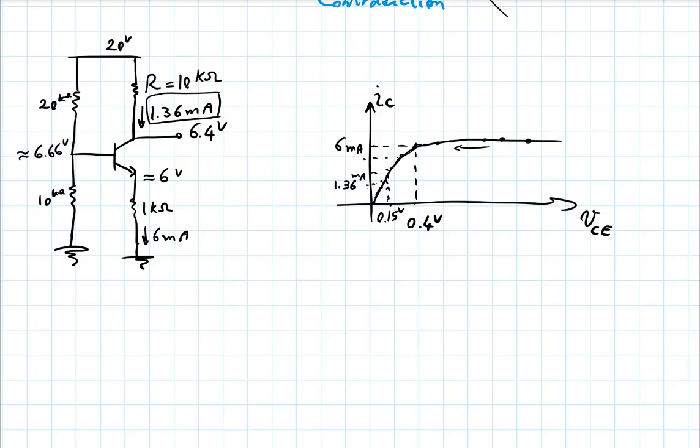This transistor is driven into saturation, and it has that kind of current at the collector. So again, to a very first order type of approximation. Recall again that a single curve like this corresponds to a single value of VBE. So in practice, maybe VBE is also changing in this process, which could make my point go from a curve like this maybe to another curve, slightly different. But again, to first order, not a big deal.